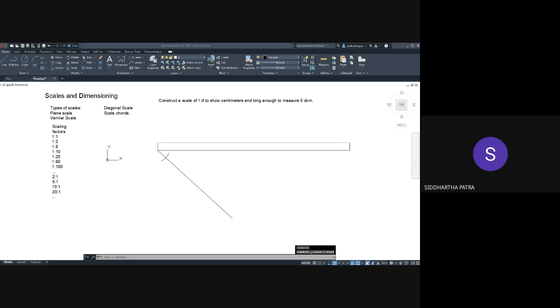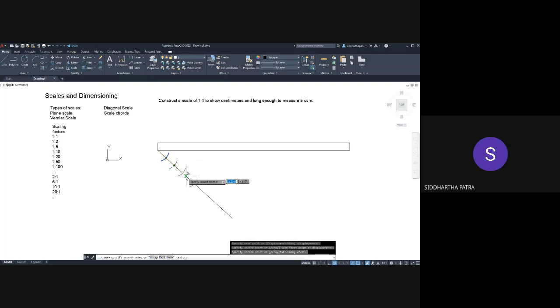Okay, so I have drawn one arc, and now I'll make a copy of those along the length. So basically, I'm drawing the arc from the first point of intersection, having the same radius. That's what essentially I'm doing. So in that way, I'll draw 5 divisions, or five times I'll cut the straight line. And this is how you divide any given line into five equal segments.